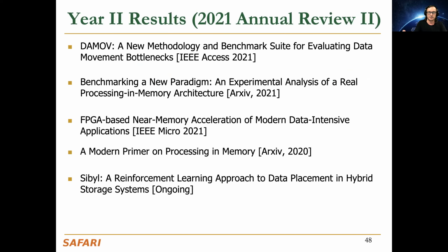Let me go to the second slide a little bit over here. We've also been looking at developing benchmark suites for processing in memory, which includes a bunch of machine learning workloads as well. And we have a methodology for deciding which tasks or which parts of a workload should be offloaded to a near data processing engine, or which part should stay in the processor. And we have a paper related to that that's recently published. I'm going to briefly talk about that, hopefully. And we have also been doing studies on real processing in memory architectures, the UPMEM processing in memory architectures, and we have detailed results related to that.